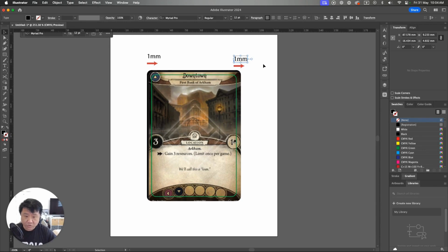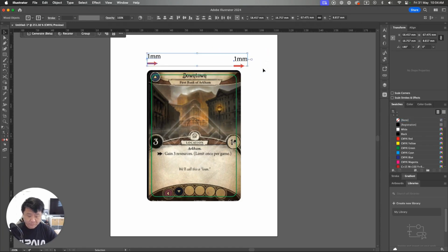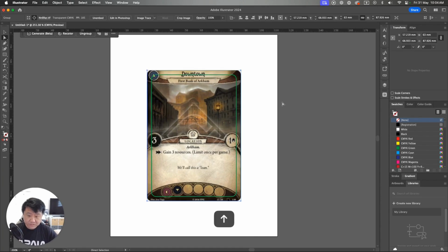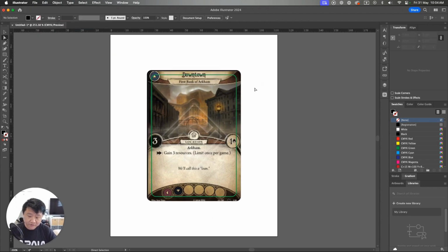And that is a good industry standard at 1 mil; I think that's actually really good. So let's see what it might look like if my tolerance in the majority of situations is, say, 0.5 mils. 0.5 mils still has a cumulative effect of 1 mil total displacement, if you will, in both axes.